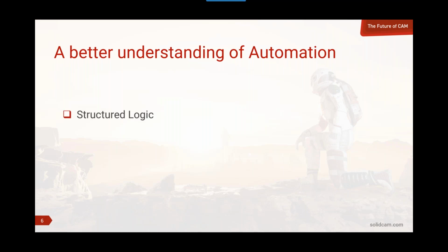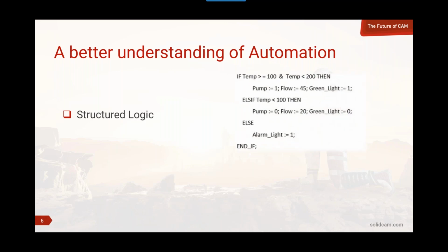And so let's talk a little bit about structured logic, okay? A lot of people are a little bit afraid of structured logic. It's not really difficult. It's pretty simple to work with if you have that mindset. Now, this particular example is a very simple structured logic statement that talks about one variable and essentially three conditions that need to be set based on the condition of the variable.